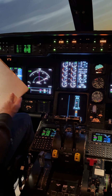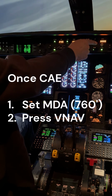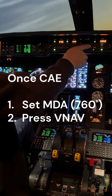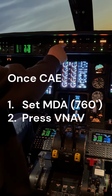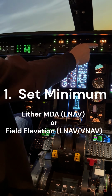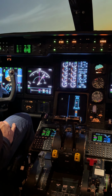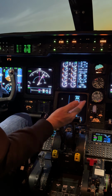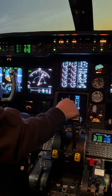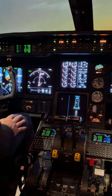After that, there's two things you have to do in this order. Set either the field elevation if you're doing an LNAV VNAV, or in this case, we're going to set the MDA, which is 760, and then press VNAV. So two things in order. Set the minimum, press VNAV. I've seen people quite often press VNAV without setting the minimum, and they flew 3,000 feet all the way through the runway.